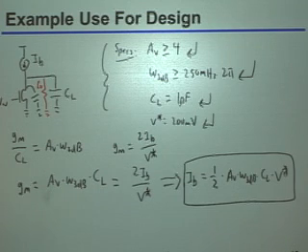bandwidth necessarily? Okay. So you asked, why can't I turn around and say that I may not have guaranteed the bandwidth? That's actually also true. So in other words, all I've really done in this procedure is guarantee the gain bandwidth. But I haven't individually specified what either one of those two are. Right now, there's really only one free parameter there, right? Because once you fix the RO, that'll set both the gain and the actual bandwidth. That's a very good question.